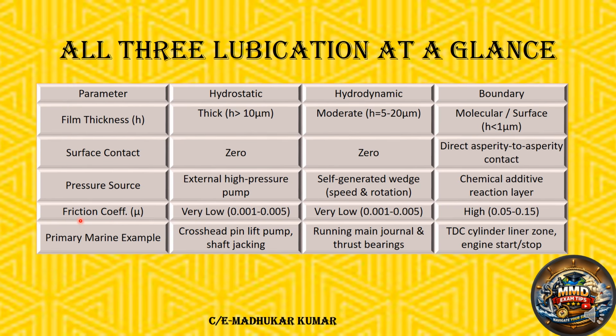What about the friction coefficient, mu? Very low in case of the hydrostatic because there is no contact, 0.001 to 0.005. Here in hydrodynamic also very low, 0.001 to 0.005. But in case of boundary, yes, it is high, 0.05 to 0.15, depending upon the boundary lubrication.